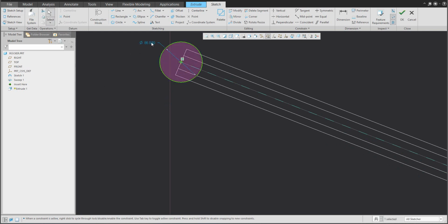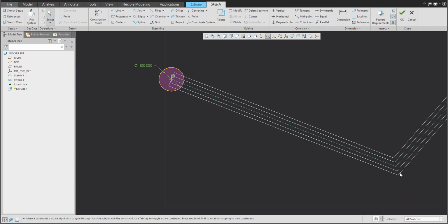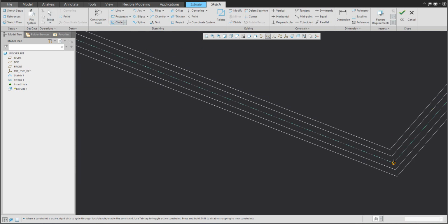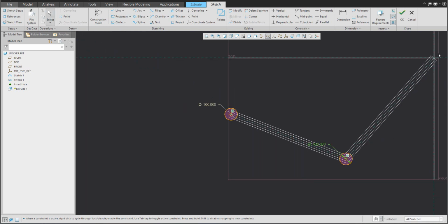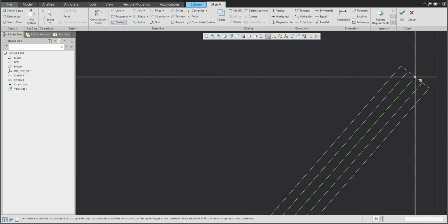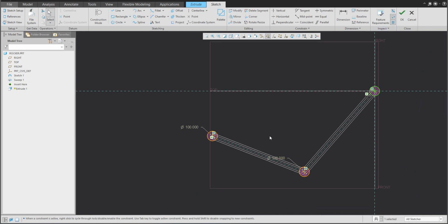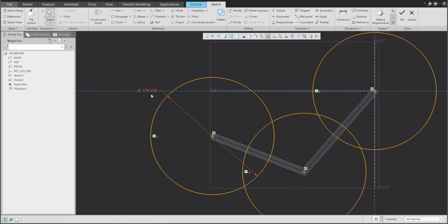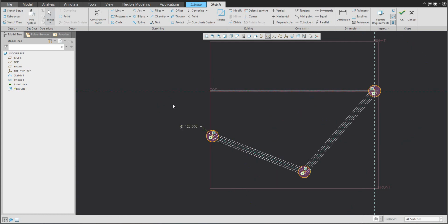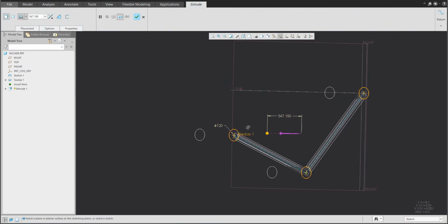You can define the 3 circles with diameter 100 and again 100. We will see, yeah? It will be necessary to change the dimension. We can change it later. No problem. Okay. If you would like to use the same, you can use equal as the reference, and the system allows you to change one dimension and everything will be changed automatically. Yeah? So if I confirm OK right now,